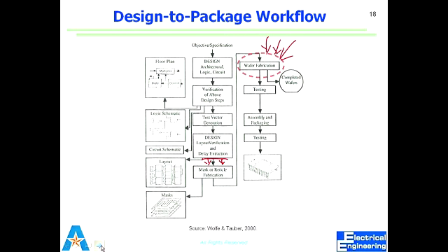When they do that layout, they have to know all the constraints or limitations of fabrication, lithography, oxidation, and etching. All those things need to be known at this part. When those are verified, they define the layout, how it should practically look: where a resistance should be relative to a transistor, where the source, drain, and gate should be, all that.